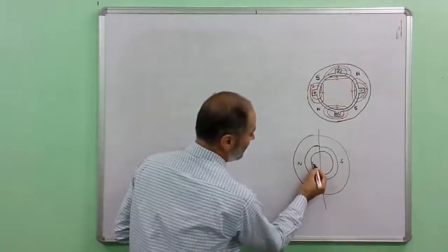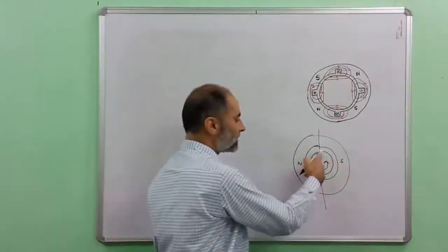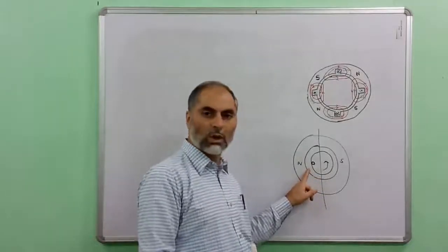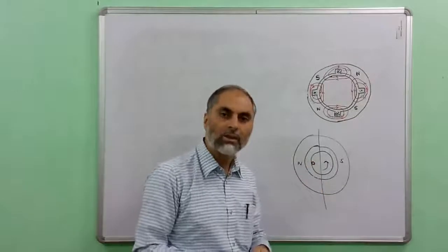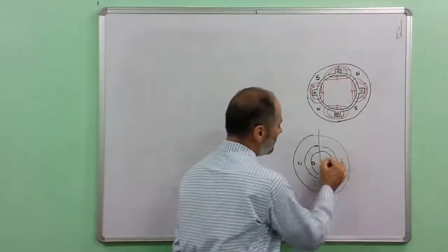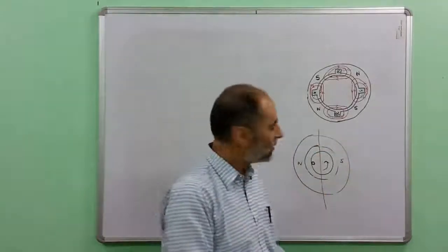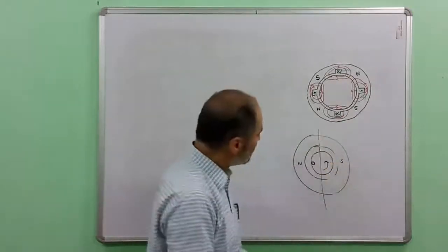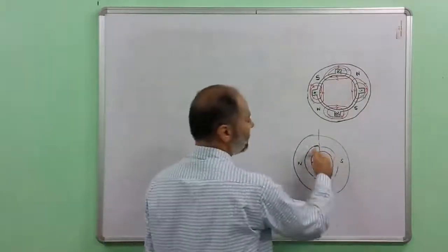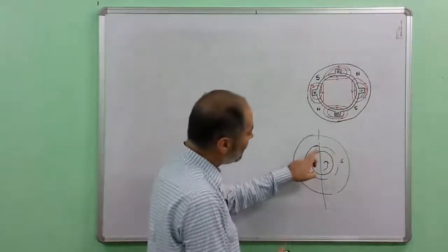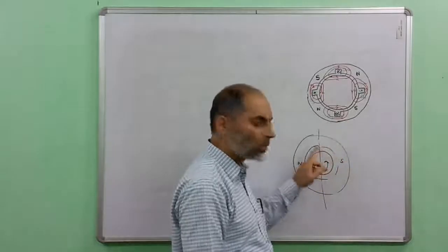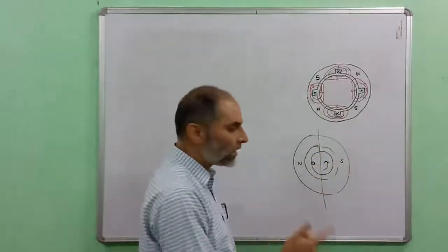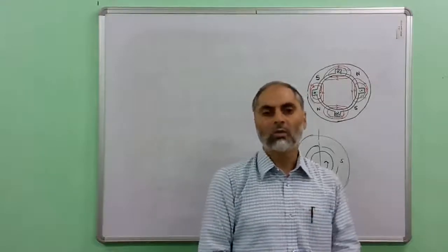If we consider a conductor on the rotor, and if the rotor is rotating, if it starts over this, while it is rotating, from this point to this point, it will be under the influence of a north pole. The EMF induced in this conductor will have one direction, and as the conductor moves from this point to this point, the EMF will have another direction, because it sees a north pole over this and a south pole over this portion. So one complete revolution of the conductor will result in one cycle of variation of the EMF. The EMF will be in one direction here, and in the other portion EMF will have opposite direction. Therefore, one revolution of the conductor corresponds to one cycle of variation of induced EMF.